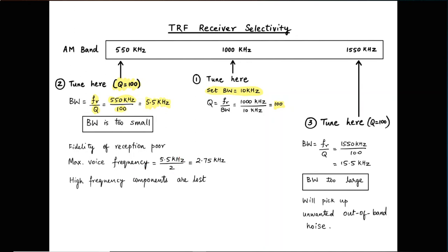Everything above that is being rejected by the bandpass filter here. So big picture, step number 2 leads to the bandwidth of the bandpass filter being too small and you actually losing the signal of interest, which you didn't want to happen.